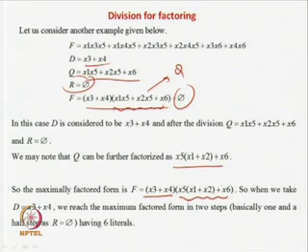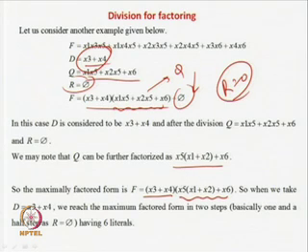So this was another example of a type of divisor. If you want to find out whether it is a good or bad divisor, you can think that this is a very good divisor, because at least you could generate a remainder R equal to 0. Basically, you can fully factorize an expression, and with the remainder 0, there are no cubes left over. So you have made a lot of saving in the implementation. Whether you can refactor again is a different story. If you can find a divisor which can entirely divide a function without leaving a remainder, you can say it is a very good divisor, because you are not generating a remainder, which means your number of cubes has reduced, so your implementation is towards the minimal.